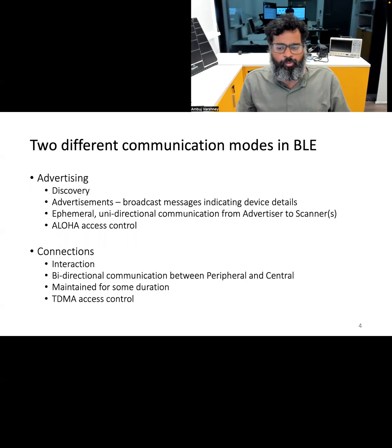On the other hand, if you want to transmit data bidirectionally and also ensure a certain quality of service, as an example, if you want to stream audio and ensure that there is no lag and you can stream at the highest audio quality possible, you would use the connection mode of Bluetooth. This mode is maintained for some duration of time, and it uses TDMA as an access control mechanism.